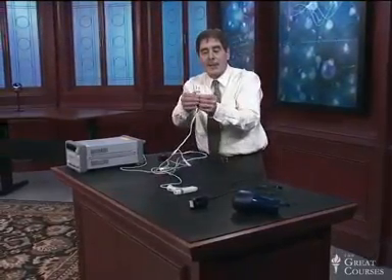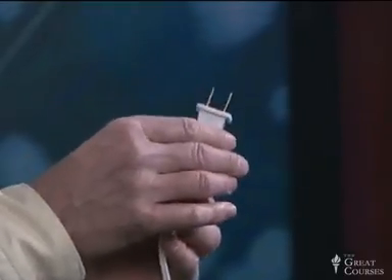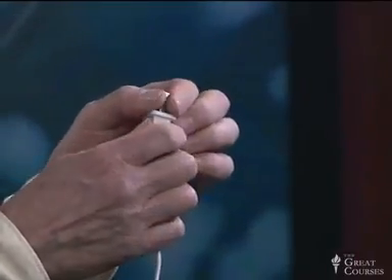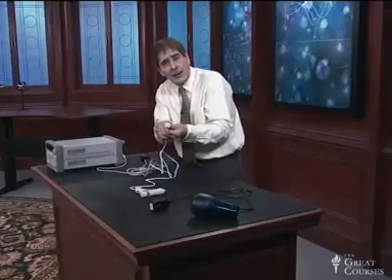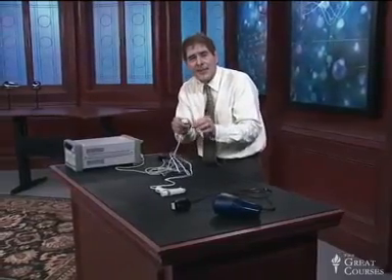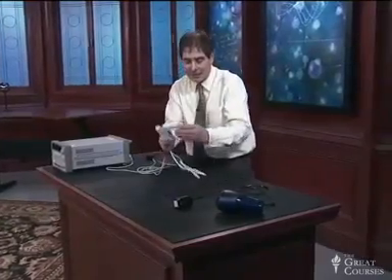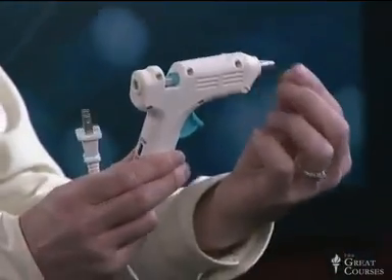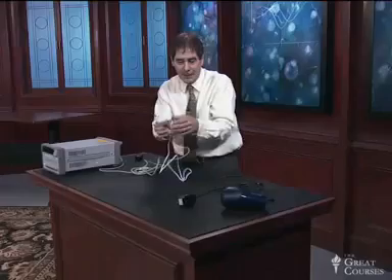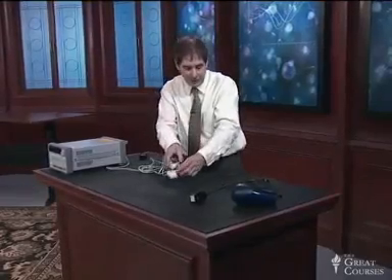Here's another way. In a lot of modern plugs, one prong is wider than the other, and that goes into the outlet in only a certain way, and that's designed to make it less likely that the hot wire is going to short circuit to any piece of metal, like this little piece of glue gun here, where there's a metal tip that might pick up high voltage if, in fact, something went wrong.